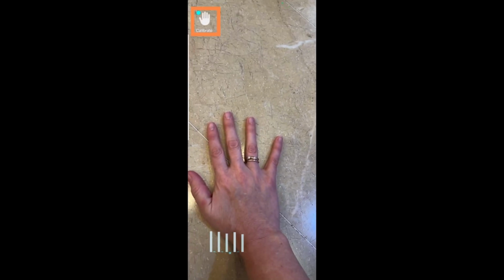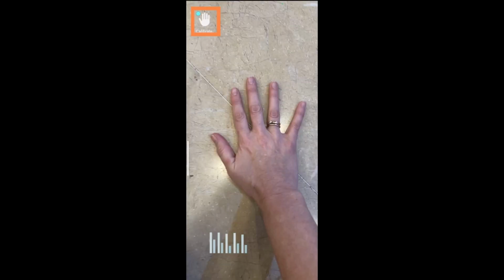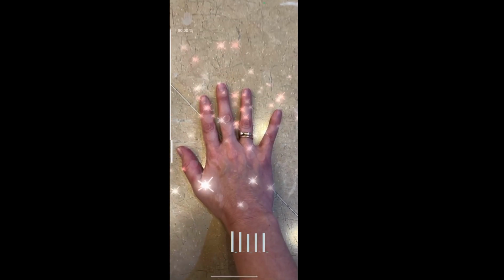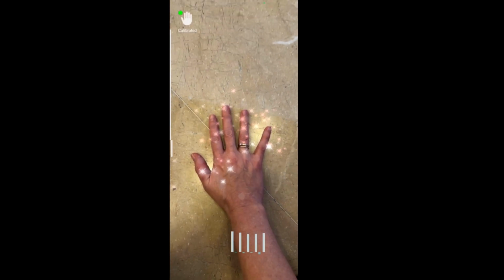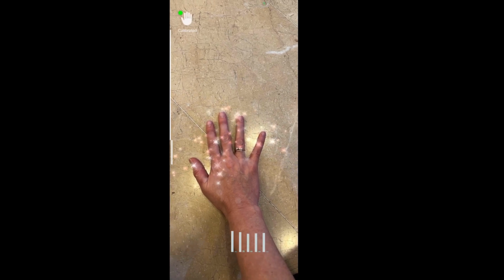After building the scene, you'll notice on the top left side of the screen a calibration button. A calibration process calculates a pair using hand scale, which is essential for accurate 3D hand pose tracking. After clicking the button, place your hand on a flat surface, point your device on your hand and move it front and back. You'll notice the calibration percentage going up, and when ready, the hand button turns green. That's it, you are all set.